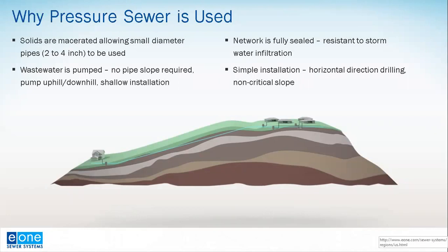The network is fully sealed. It's resistant to stormwater infiltration. It's a simple installation, relatively speaking. Again, horizontal directional drilling is often utilized, and it requires no critical slope to work.